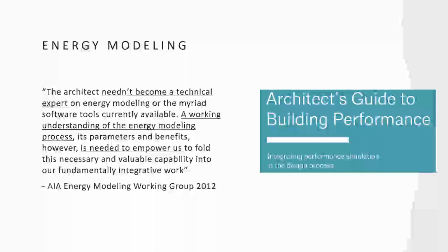I mean, there are going to be certain checkpoints in a design process where you have to stop and collect information. So like, what is your U value? What is your R value? What are your material specifications? How's your building form, your building shape, orientation? Stopping and documenting those, handing those off to the proper people, whether it's inside your firm or a third party, and giving you those makes that a seamless transition so the energy modeling process can begin while you're still doing the design process.